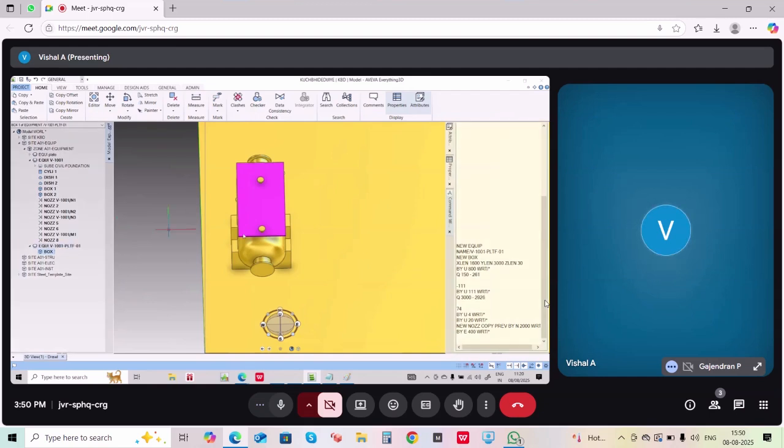Now, why am I creating the ladder inside this platform equipment? Because this ladder belongs to this platform only. So I will go and create a cylinder: new cylinder, enter the height and diameter. Always remember the cylinder diameter will always be 800 mm.